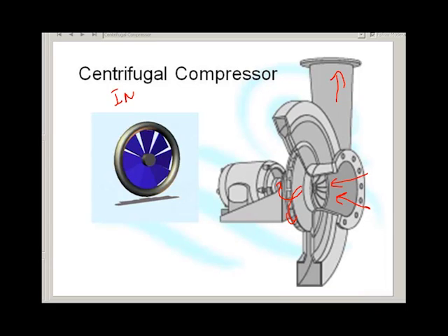They're called inlet guide vanes. And this is an inlet guide vane. The inlet guide vane sits at the throat here. And what it does is it opens and closes like blades on a propeller feathering, and it allows the air to come in, or chokes it off basically.